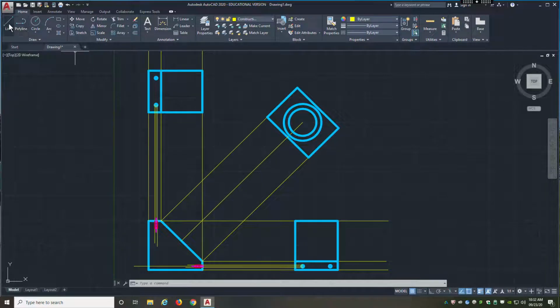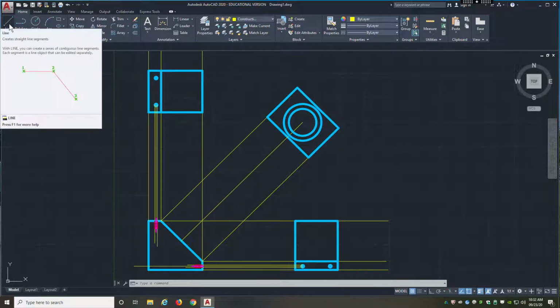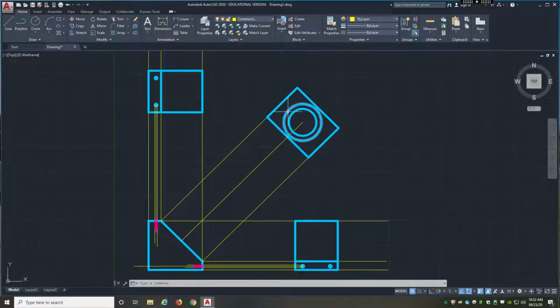Okay, so actually we can do it a couple ways, because the quadrant, right? Actually, if we try doing quadrant, which on an angle would be somewhere over here, AutoCAD doesn't know that. So it still sees the quadrant, the north quadrant here, and the side quadrant on the side. So that's not going to work. So the best thing to do is to continue using your offsets so that we can offset the lines to the circle. So we're going to offset this center line to either side to help us get that information.